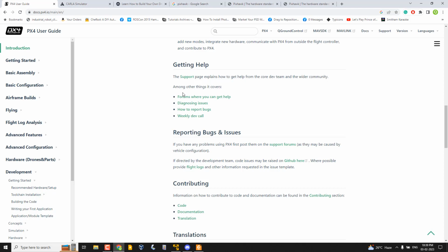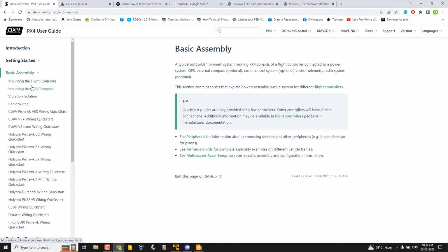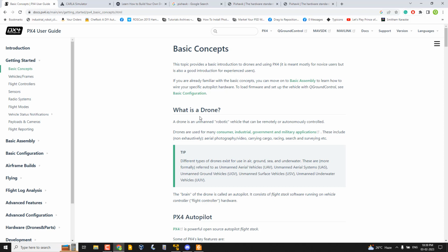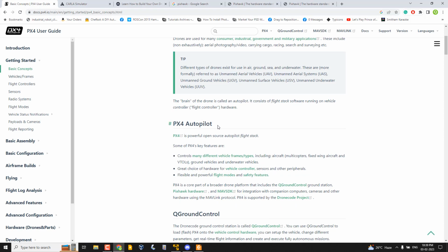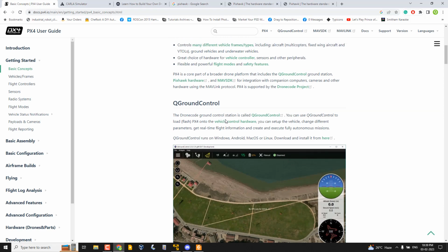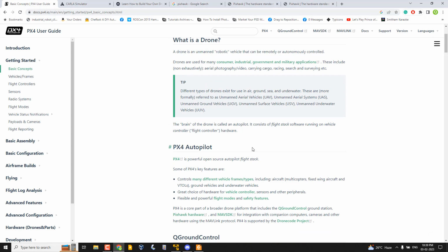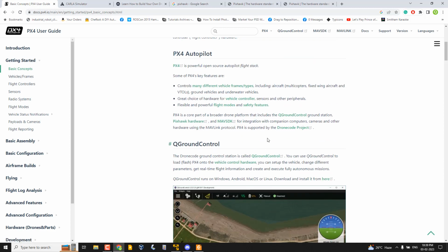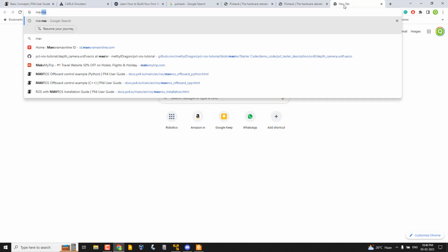That is how most of the people are doing drone building, using an easier way. Okay, this is an easier approach. You have to purchase the Pixhawk board, set up the PX4 firmware, and connect the Pixhawk board to ROS, using a project called MAVROS.